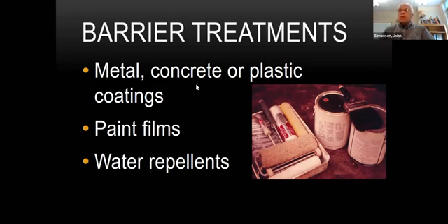But in your yard, you can sink the post into concrete. You want to be a little bit careful that you don't create a water trap so that the post rots off. So you need to either leave the bottom open, push it through the concrete, or bring the concrete above ground.